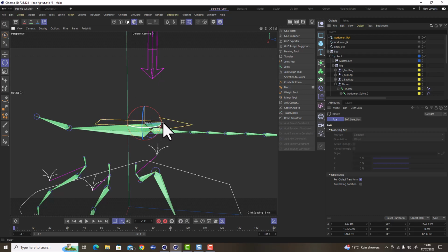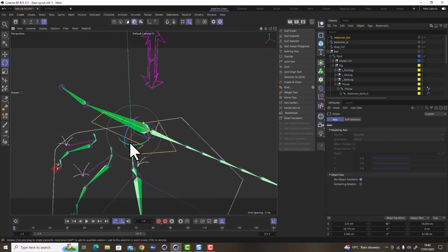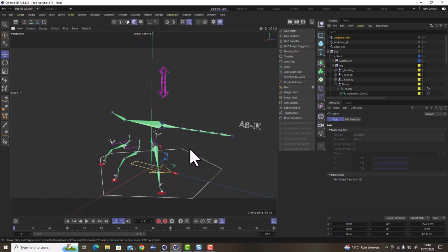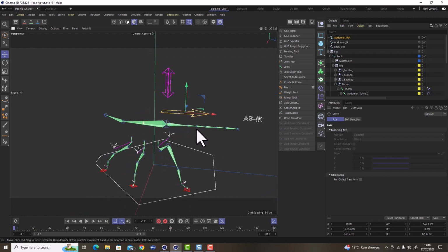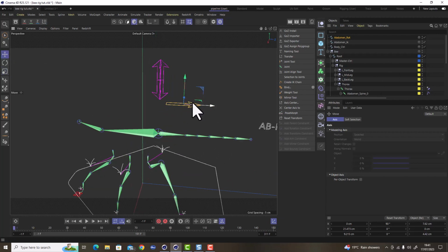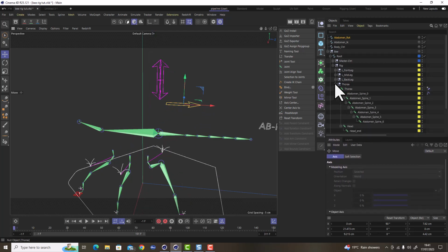Shift key will help lock that into place. And that's get the Z axis. In fact, that's get all of these centered off. And we don't need this as big as that, but what I do want to do is create a nice curve to it, and to do that I'm going to use the geometry and the project tool.